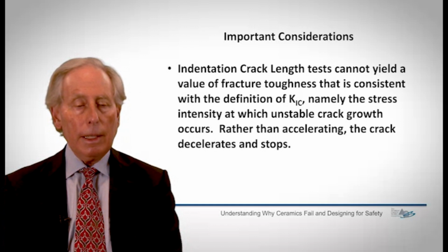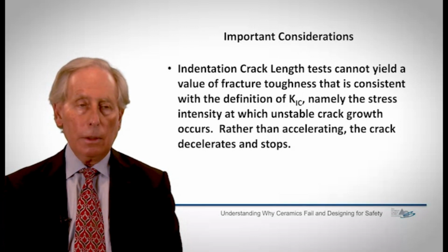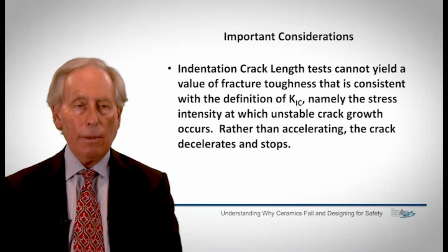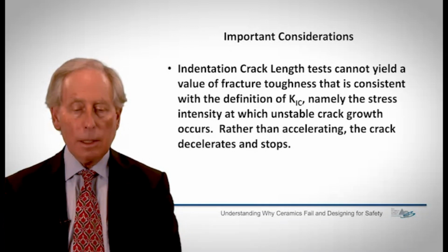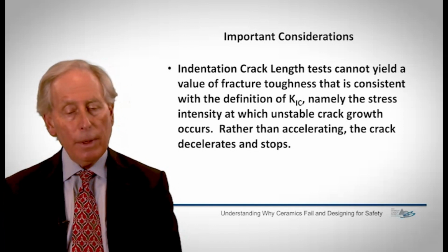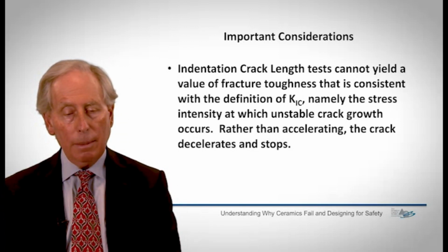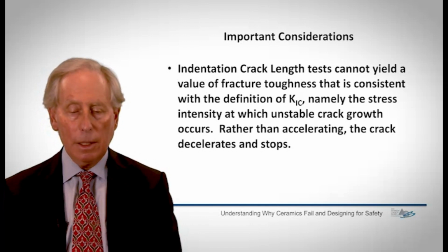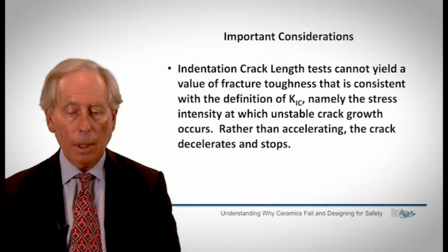It's not really consistent. The number I get for stress intensity or fracture toughness can't be really consistent with that definition I gave earlier, where the crack grows rapidly at the point of criticality, because in this case the cracks grow quickly at the beginning, slow down, and then stop. So sort of by definition the two numbers are not going to be quite the same. Will that make a difference? Maybe, maybe not, but one should recognize that I may not be getting the same kind of number.